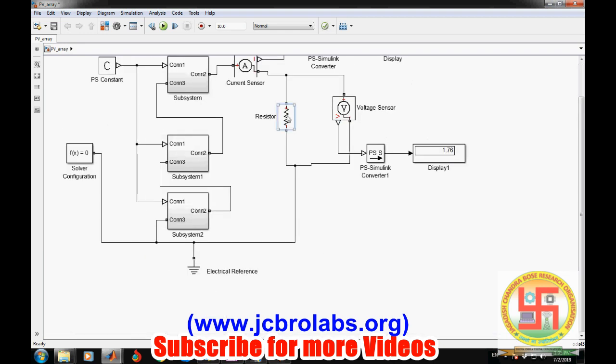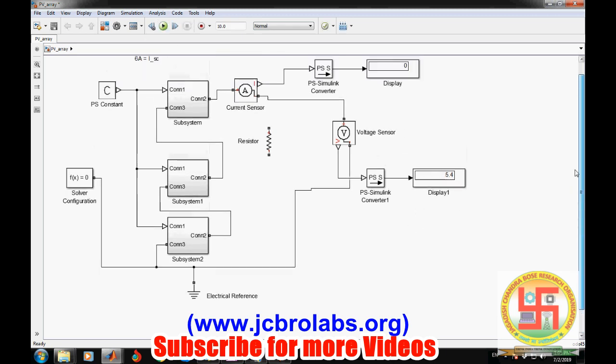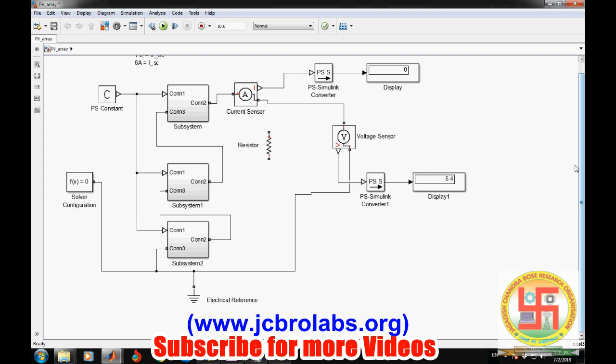Now let's see how much open circuit voltage or short circuit current we are getting. Because we have connected in series, the short circuit current will remain the same. There will be only a difference in the open circuit voltage. Now the open circuit voltage has increased. So this is how we can create a larger subsystem, each comprising a series and parallel combination of solar cells. I hope you like the video and you understand a lot from it.